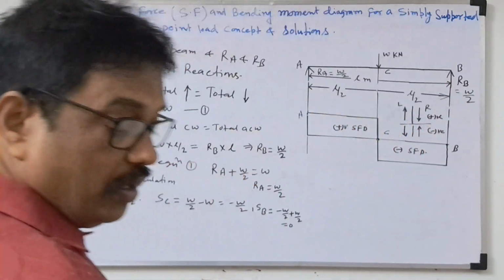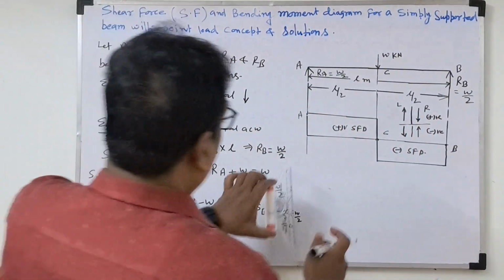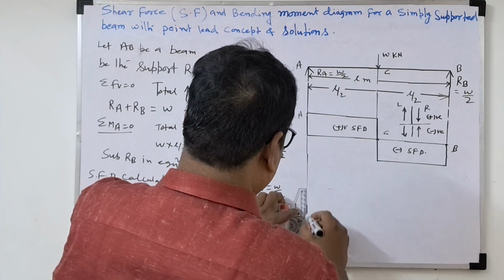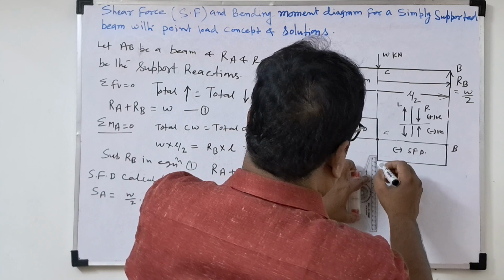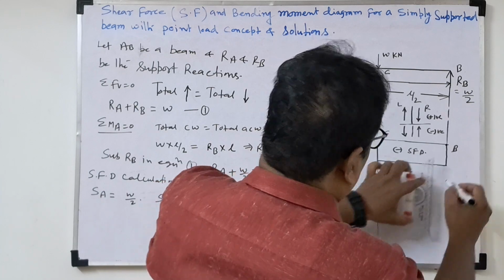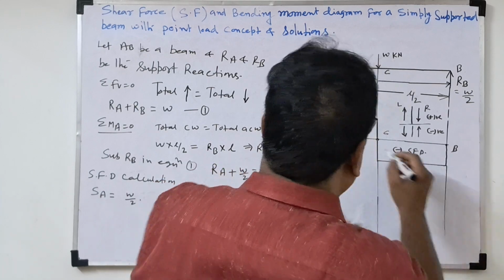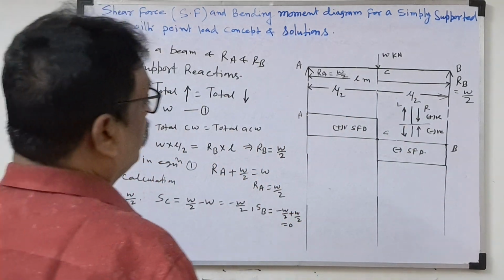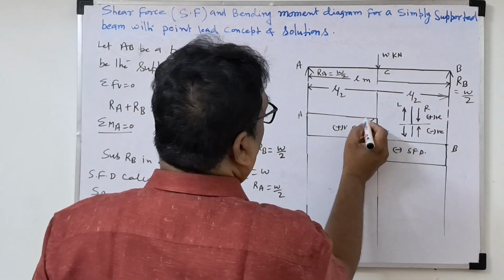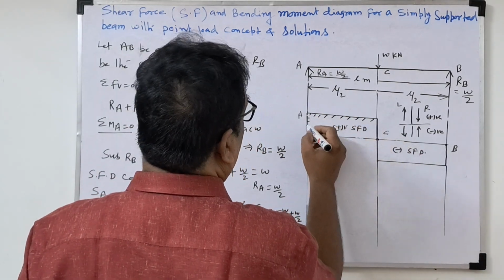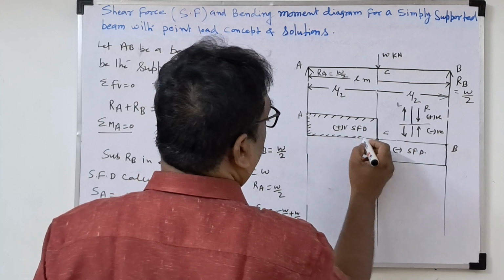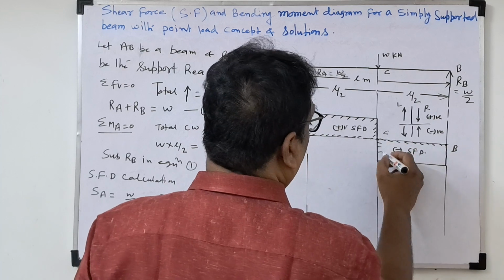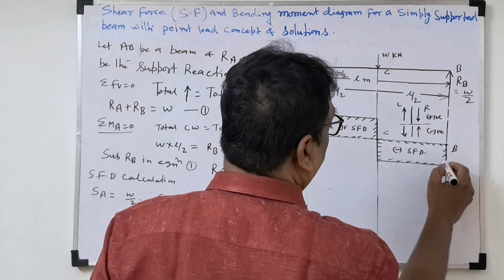So now we will calculate the bending moment. So the line will extend this. So we will draw the bending moment. A light line you have to draw by the pencil. So already you know where the shear force is 0, bending moment will come maximum. So okay, now the bending moment diagram. This line you hatch it because this is the shear force diagram that came now. So you hatch it. This is the shear force diagram.